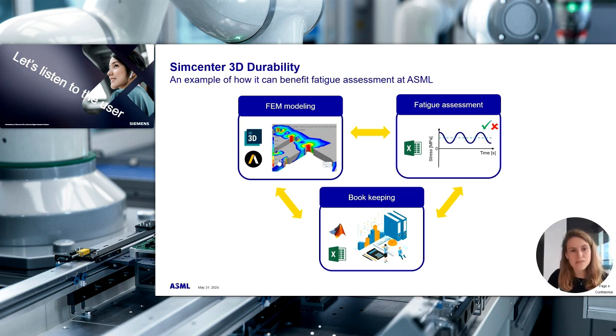And it turns out that it's possible to follow the exact fatigue assessment way of working from the Excel sheet also in durability. So the Excel sheet is not needed anymore. I updated the logo now with Simcenter 3D durability. And also what really helps is, since you can directly perform fatigue assessment on your FEM results, you need less bookkeeping and an external tool, but you can also again immediately keep the overview of your assessment within Simcenter 3D durability, and that's also a big advantage.